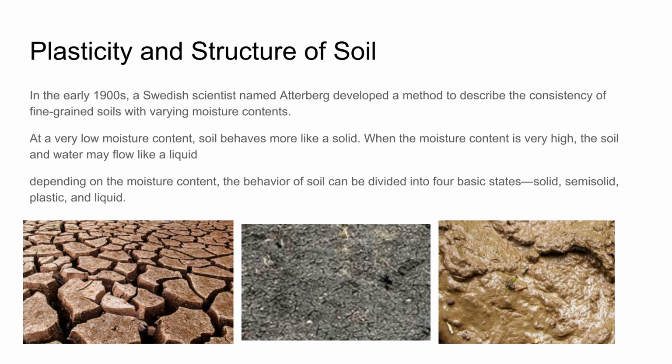Atterberg developed a method to describe the consistency of fine-grained soils. Depending on moisture content, soil behavior changes, dividing into four basic states: solid, semi-solid, plastic, and liquid. These states define the plasticity and structure of the soil.